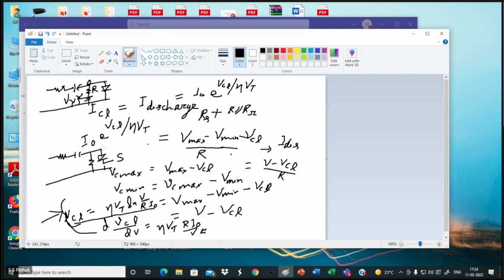Diode is forward bias, reverse bias as usual, the way it is coming. Now I am putting a switch. So when the switch is open, it is working like a high pass filter. I am getting the output. When the switch is closed, it works as a clamper. So this becomes synchronous. This will be synchronized with the input given to the switch. Synchronous clamper.